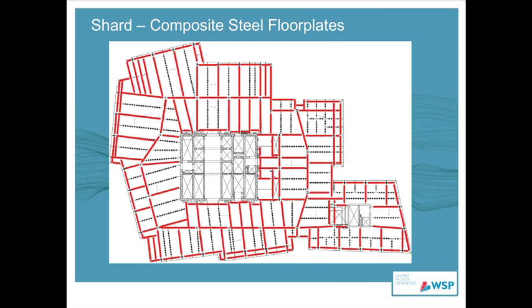So in terms of what we end up with, this would be a typical fire protected scheme. We would have protected beams between columns. Also, if you look at the service risers around the main core, we would make sure that any steelwork used in supporting those critical areas, where you could have a compartmentation breach, was protected. All the beams that were protected were 90 minutes fire protected. That was on the basis of a time equivalence type study where we reduced the fire protection required from 120 to 90 minutes, which is a common technique used on most buildings in London.